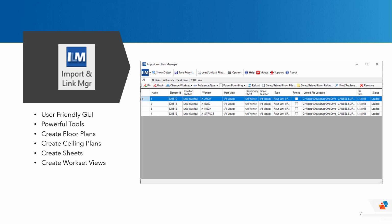So I don't know how many project files, again, I've seen that have DWG files inside of them, but it's a lot, and those imports can be pretty hard to track down, especially if we import a DWG into a single view in the Revit project file. This tool has saved me a lot of time over the years identifying these files and removing them from the project. Once I've confirmed, of course, with the project team that the file is no longer in use and good to be removed.